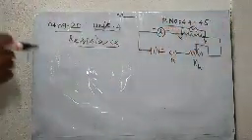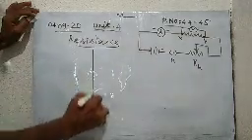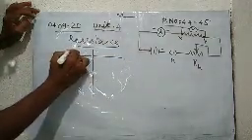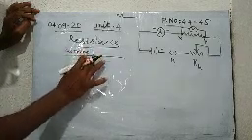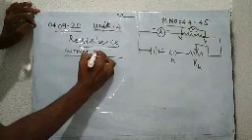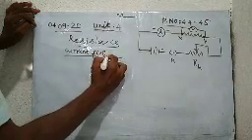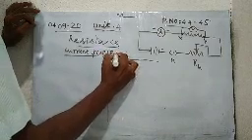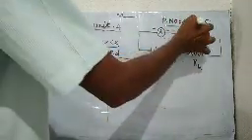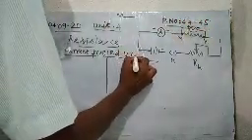Then by changing the rheostat, the current flowing through the conductor is varied. Then the current flowing through the conductor, which is represented by I in ampere, is measured. Then the potential difference across the conductor is measured by the voltmeter, therefore V in volts.